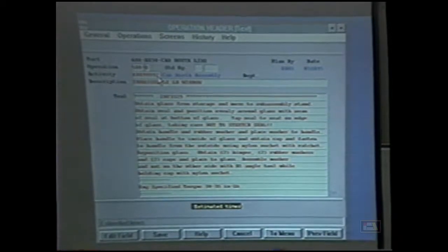So it allows us to process all this variation and have different parts lists for different alternates, but when I get to line balancing, I'm going to take all the 580s and assign them to one man on the line, and I'll show that later. Then I suppose you could talk about times briefly, because each of these alternates can have different times, and then you need to specify what's going to be your control time for line balancing. Right now the system defaults to the high time, but you can also flag any time as your control time. So if your Euro option is 3.5 minutes and your North American is 3 minutes, but your Euro option is so small it doesn't matter, you can flag the North American alternate to be your control time in line balancing. Probably getting way ahead of myself and way too deep right now, but hopefully some of this will become clearer as I go on.